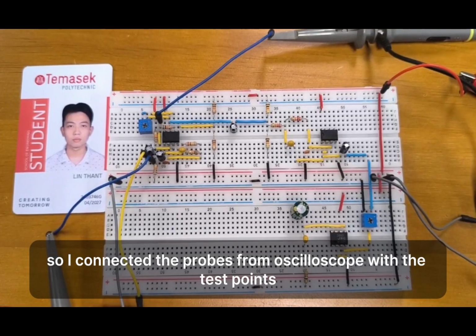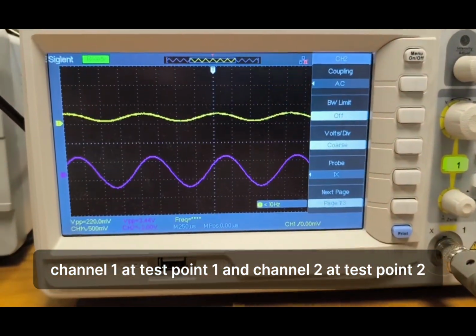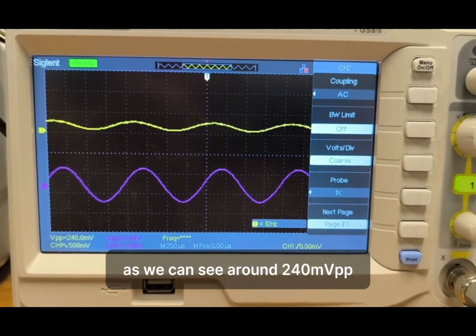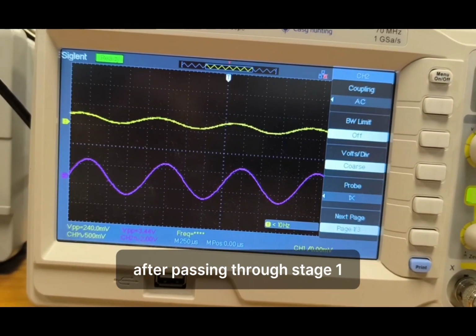So, I connected the probes from the oscilloscope to test points in my circuit, channel 1 at test point 1 and channel 2 at test point 2. As we can see, around 240 millivolts peak-to-peak from test point 1 is boosted to around 3.4 volts peak-to-peak at test point 2 after passing through stage 1.